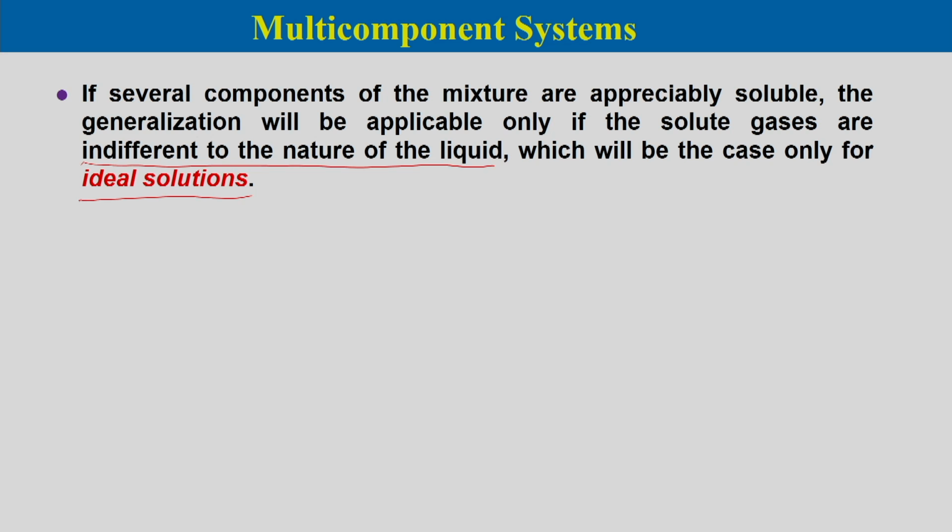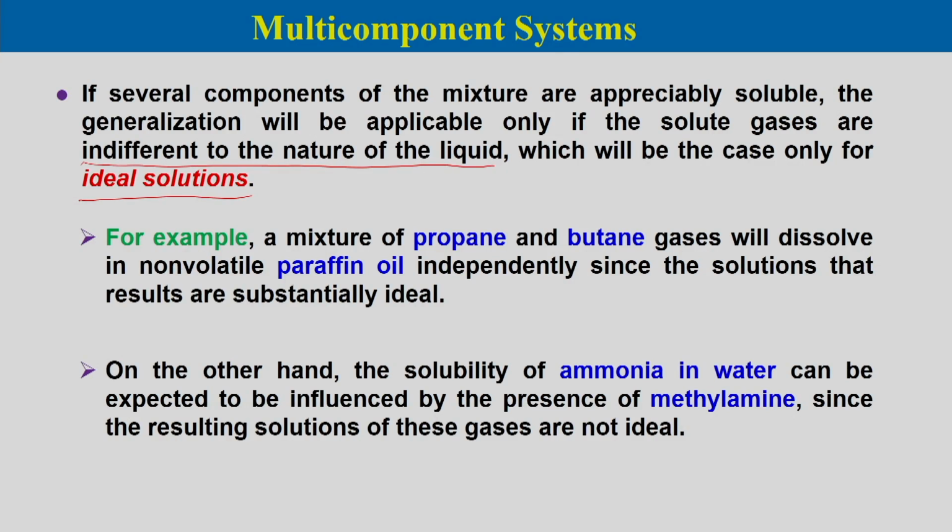So, although you have multiple components A, B, C, and all of them are appreciably soluble in the liquid phase, if they form an ideal solution, then the solubility of one component will not be influenced by the other component. For example, a mixture of propane and butane gases will dissolve in non-volatile paraffin oil independently, since the solution that results is substantially ideal.